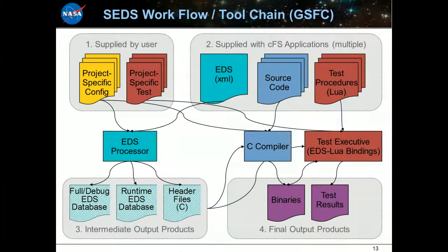One thing we did, we used Lua, and we were able to take the data sheets and actually generate tests that we could do in situ on the processor to test all the command paths, all the command interaction patterns, all the telemetry interaction patterns. Essentially, we autocoded much of the software and all the tests, and then generated all the artifacts from that, which is pretty powerful.